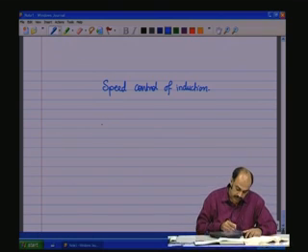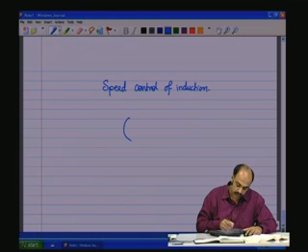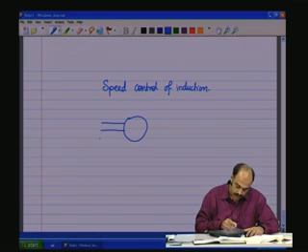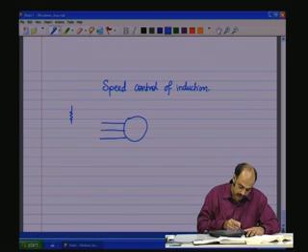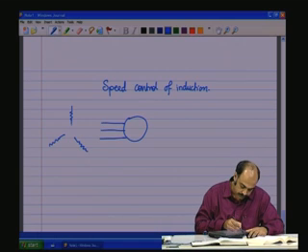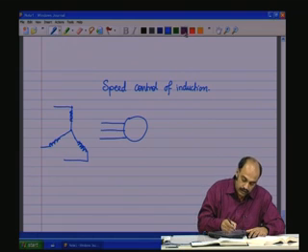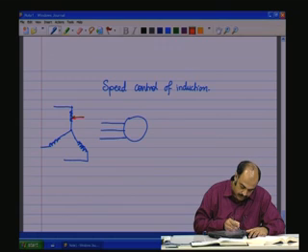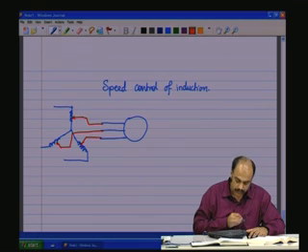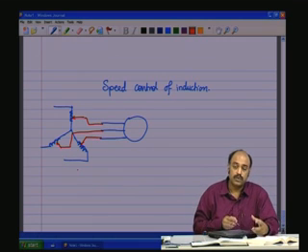And using the auto transformer for the stator of the induction motor, using a three phase auto transformer, let us say you have something like that, all these are connected like that. So these are the windings. And you can tap equidistant from all of them and give it to the induction motor, and you can do stator voltage control.